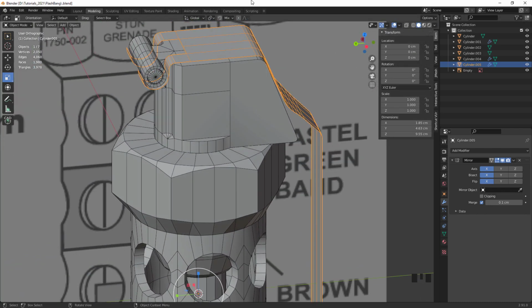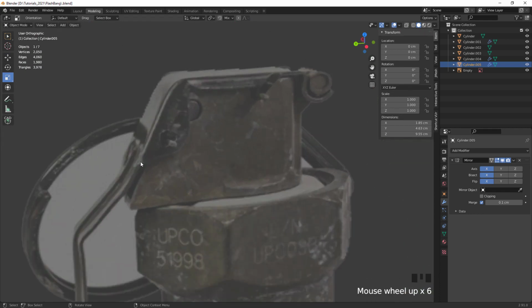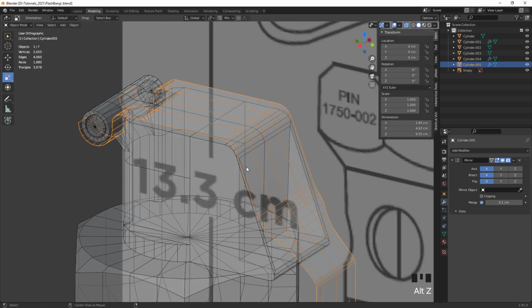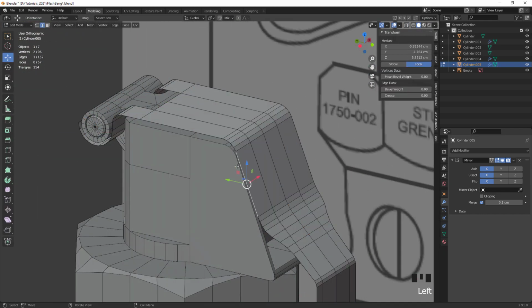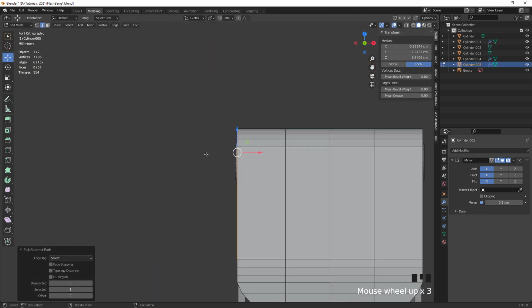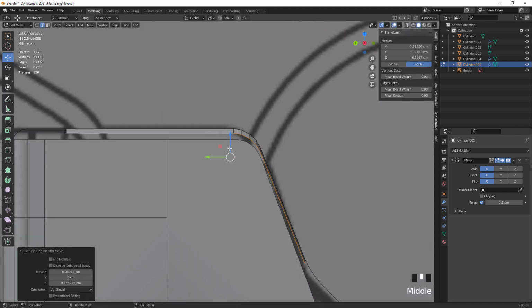So as a next thing, let's work on these elements that are folding down here from the sides. For that, we already have our edges in place. I'm gonna select this edge and then press Ctrl to make a connected edge loop there. And then with D, we extrude it out here to the side.